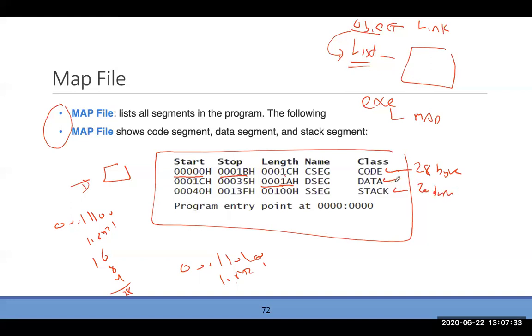Maybe you're declaring some variables there that are going to take that space, and so on and so forth. So the .stack right now, what does it take right here? It takes a large space, right? If you look at it, this is going to be 0000, right? So this is going to be your 256, right? And then you have another 0. This is 256, right? And then you have a 1 in here. Okay, so if you calculate this, you're gonna have almost 4096 bytes for the .stack. So this is what you're gonna have in the map file, okay?